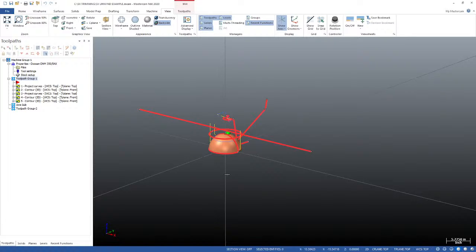So a vector-based toolpath is a series of tool positions in 3D space, and between the endpoint of the last position and the next position you're given, the tip of the tool is going to move from point to point, so XYZ to XYZ.